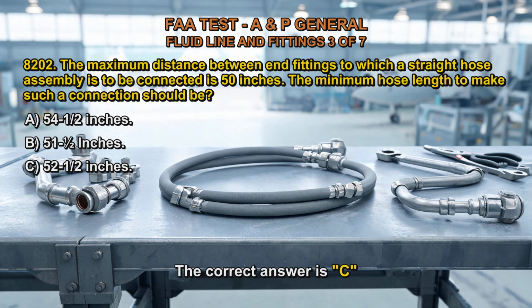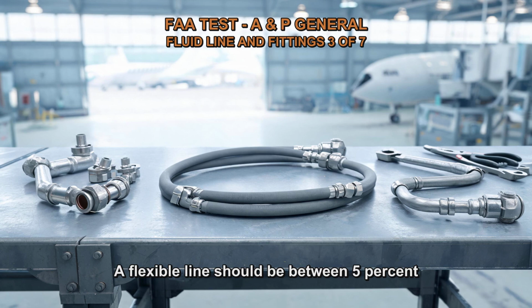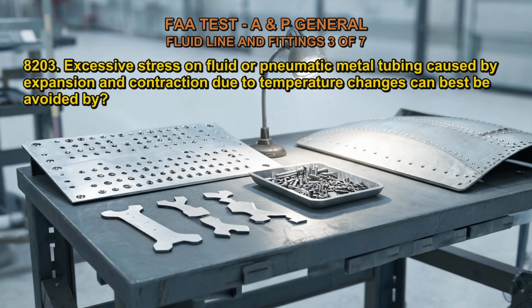The correct answer is C. A flexible line should be between 5% and 8% longer than the distance between the fittings when it is fitted in a fluid power system. The hose should be at least 5% longer, or 52 1/2 inches, than the fitting's distance of 50 inches.